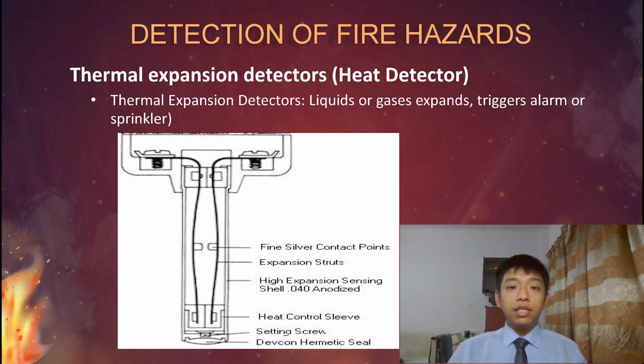I will present the detection of fire hazard. The first is thermal expansion detectors, heat detectors. This detector is a normally open device designed for fire detection and alarm systems. This detector will trigger an alarm or sprinkler. This detector operates on the principle of a rate compensated detector.